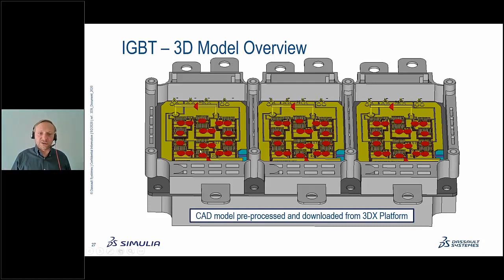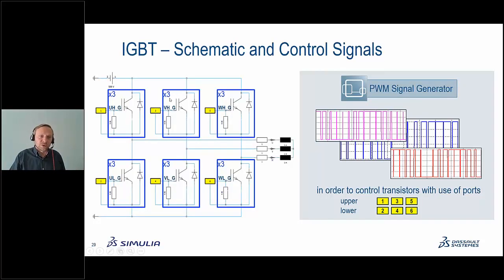We have 3 high-side transistors here, here, and here, which gives us 9 high-side transistors and 9 low-side transistors. The aim here was, of course, to split the current between them in order not to have any thermal problems. So this is the setup we have. That's why it says ×3. So we have 3 transistors in every phase. I mean, 3 transistors on the high side, 3 on the low side for every phase.